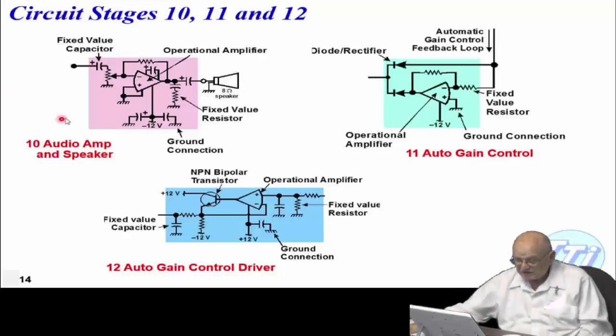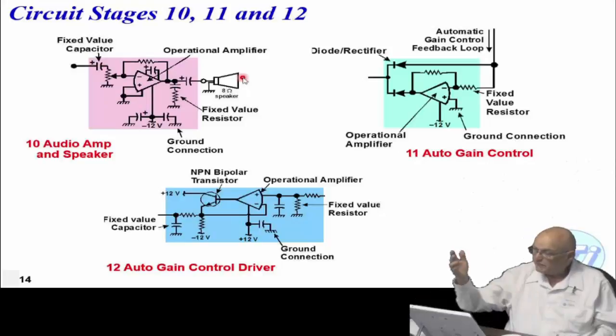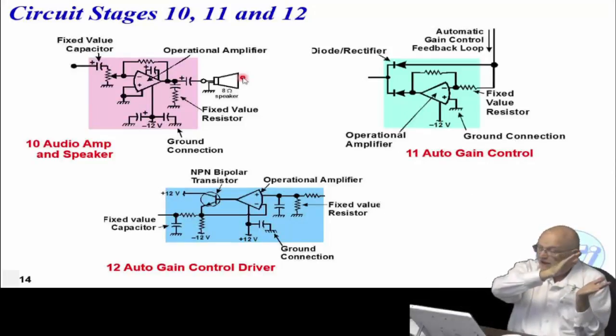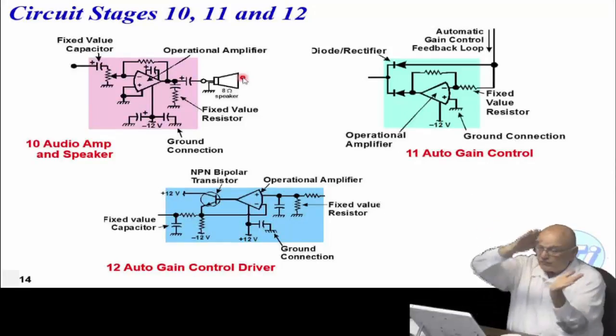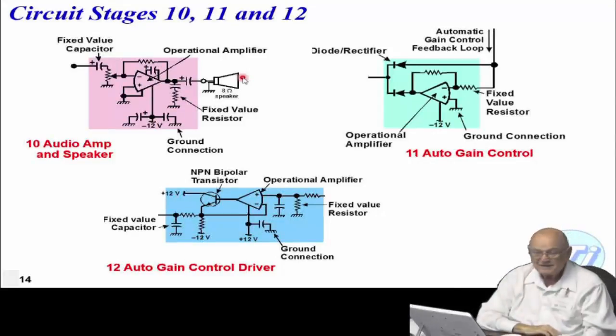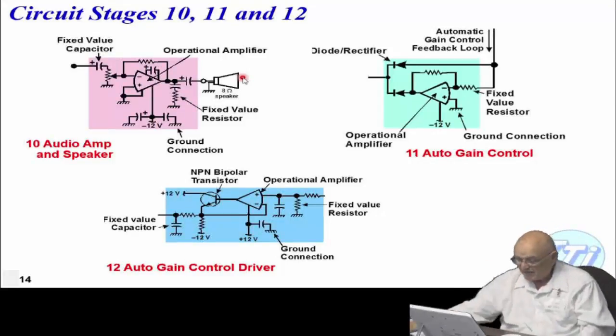And then you've got, essentially, the audio amplifier and speaker. Now look at this. This is an 8 ohm speaker. That 8 ohm speaker is matching this 8 ohm output impedance. You notice the taper you have on the speaker? That's 8 ohms back out here in the beginning of it. This tapering of the cone will match the 377 ohms to air. That's why it's tapered. In RF frequencies, you'll see a horn. You might have mentioned that. That horn is tapering from 377 to 50 ohms in the RF frequency specifically.